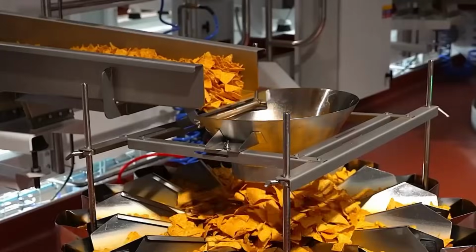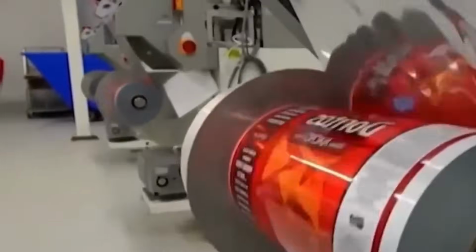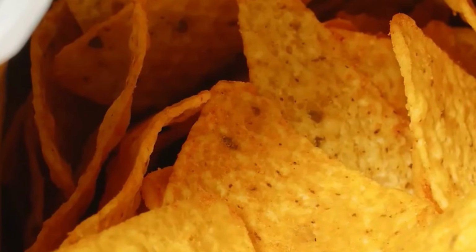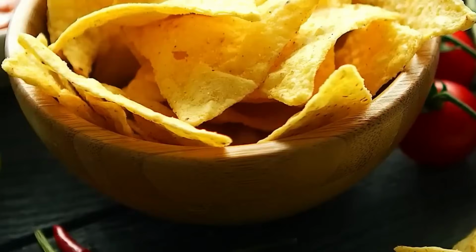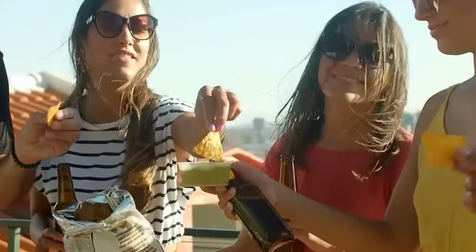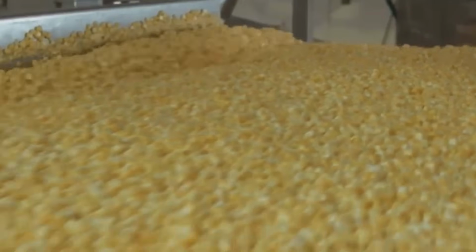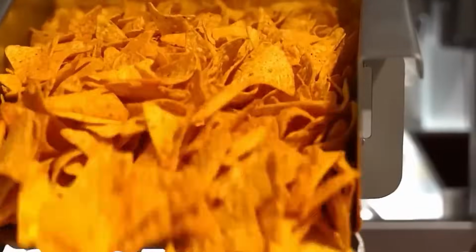Packaging lines operate at speeds between 60 and 150 bags per minute, depending on bag size and configuration. Packaging materials are stored in automated reels with sensors that alert operators when a roll change is needed. Packaging seal integrity is tested using vacuum or burst testing at specified intervals. Seal strength and print registration are logged alongside product weight and metal detection data.